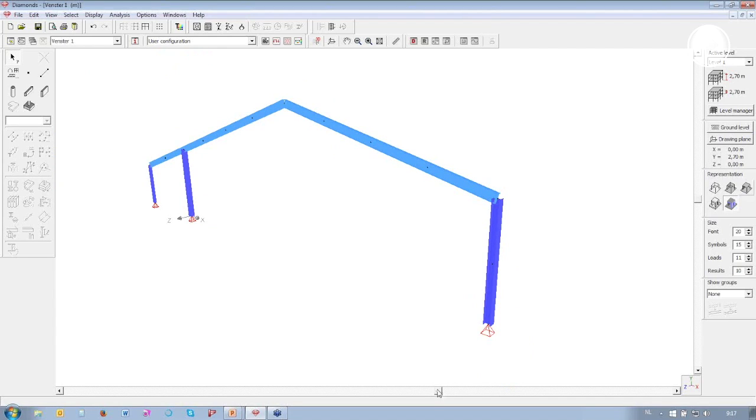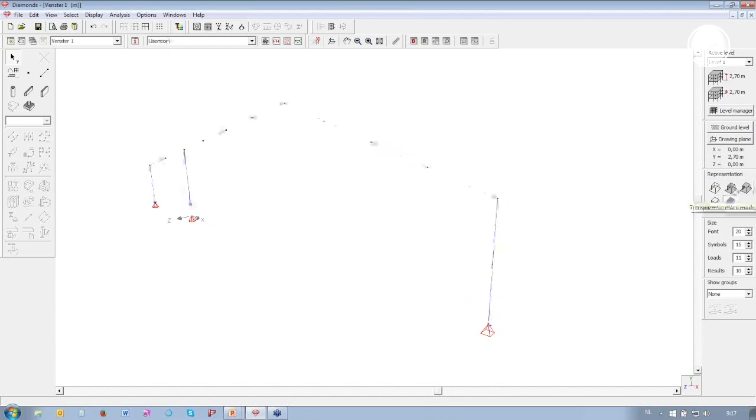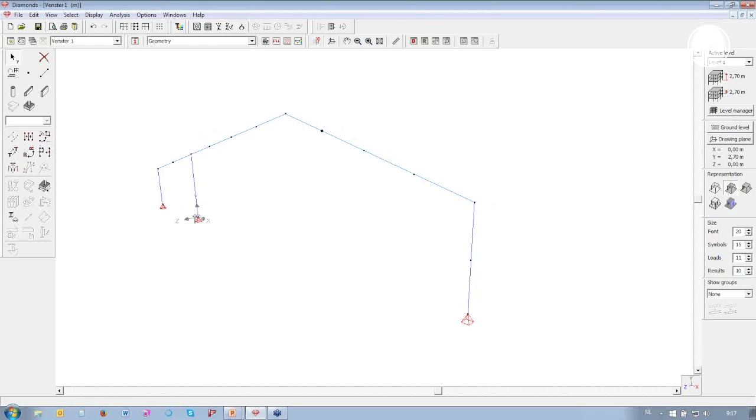Concerning the purlins right now, we have represented the purlins with the intermediate nodes. Now, if you look at the model right now in 3D, and we would give a little push in the Z direction on this frame, just a very, very little push, you can clearly see that the frame will fall over, will flip over. It's because there are no supports currently.